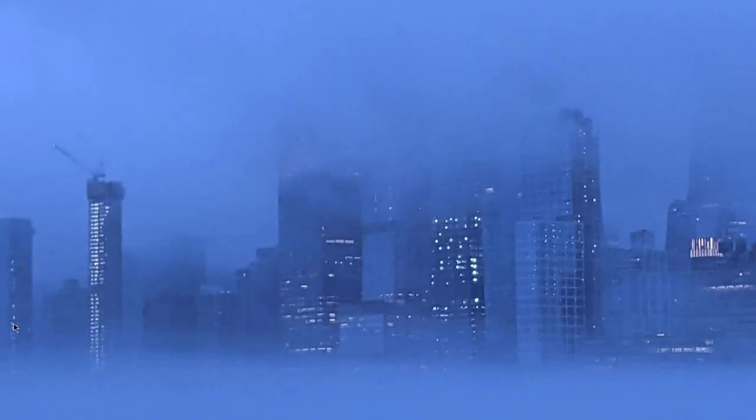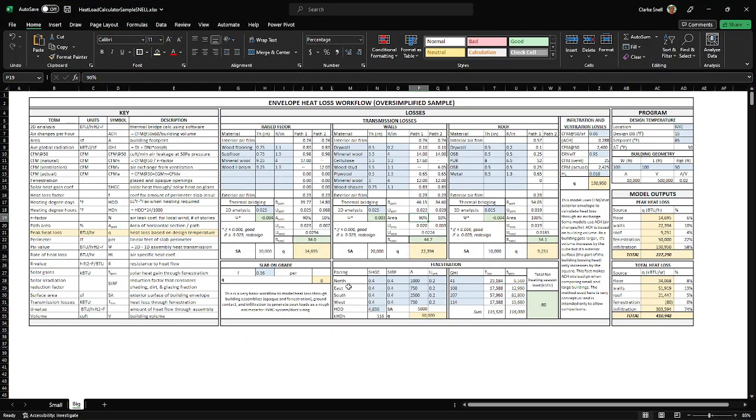Okay, so back to this, and then we were here, and that's where we got the 90 and the 10%. And so then we get total U values based on the percentage of each of these paths, and then we add them together, and we get a U value total. I went ahead and did an R value because I like seeing that, because I think in R value more than U value.